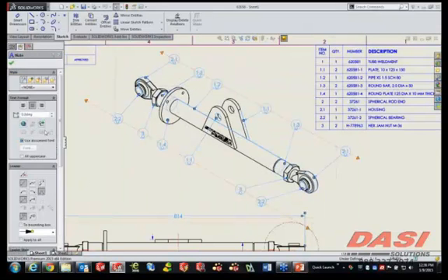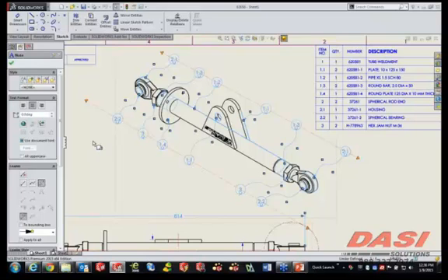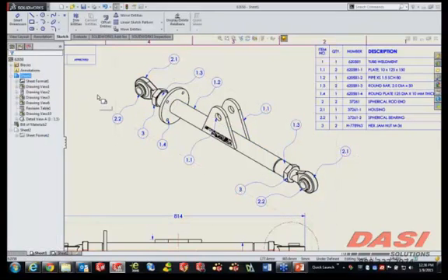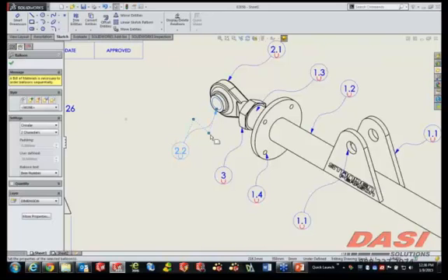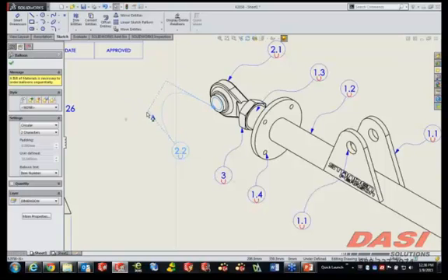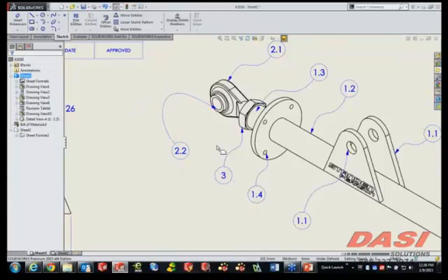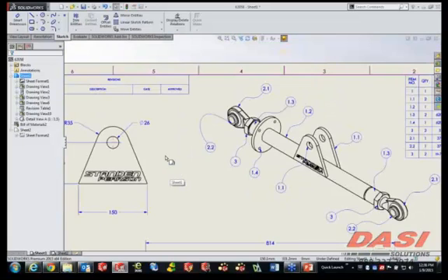If we go to more properties, you'll see it right down here. It's called the spline leader. The spline leader instantly converts all the selected balloons over to a really nice little squiggly look. And this is really what you'd see, I think, if you're looking at pattern drawings more often. Now these splines happen to be style splines, so you can change those any way that you'd like by manipulating the handles around those, so they are quite flexible in their layout.